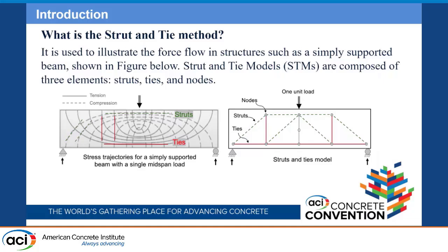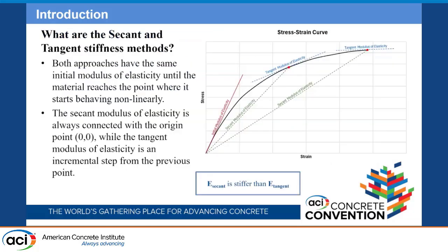So we had some papers that were published recently that adjust or correct the linearized strain profile. Here, the main contribution of this study is we didn't need to touch strains. There was an innovative way of approaching the estimation of the yielding point and the estimation of the ultimate point. So we were able to capture the full response of the beams without messing with nonlinear strains as an estimate.